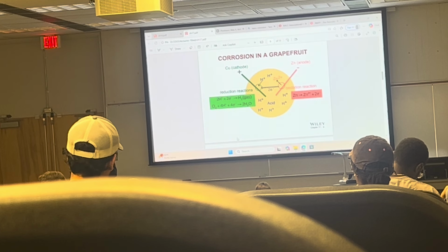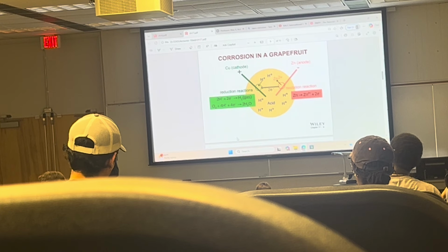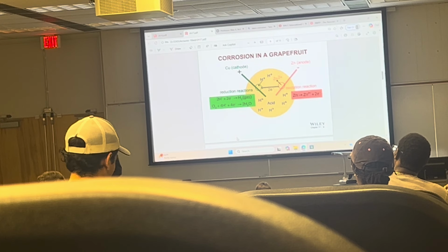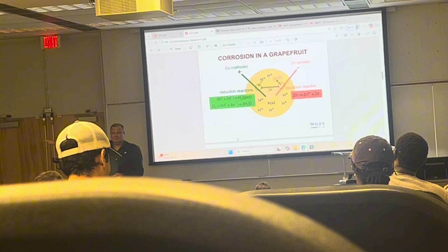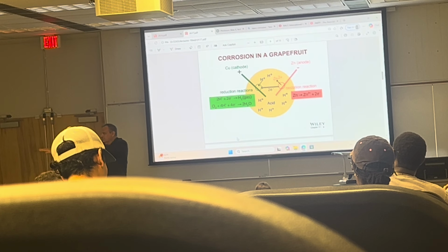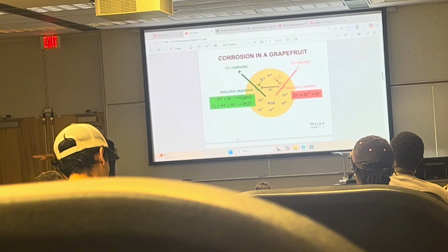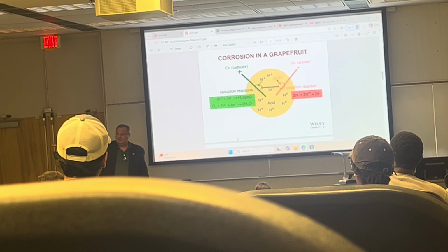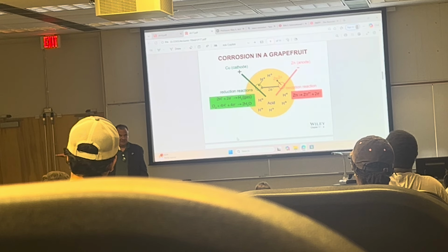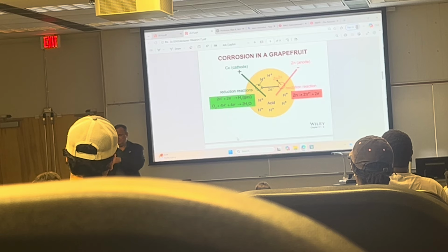Okay? All right. Now imagine there is a balcony. And it is a cantilever balcony. So this is a cantilever. And you're walking on it. Where would you put the rebar in that case? No, in this slab. So this is a slab. On the top. Okay, so you would put the rebar on the top. And the closer the better.